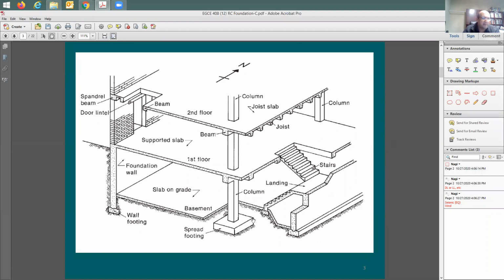So you need to have a footing here. Otherwise, this column is going to be penetrating the soil. Also, you need to have this footing to be able to make this member here stable. You cannot just have a column that sits on the floor or on the ground, on the soil, without having dimensions like length by width. The problem is going to happen if you don't have it. Again, the column is going to be penetrating the soil.